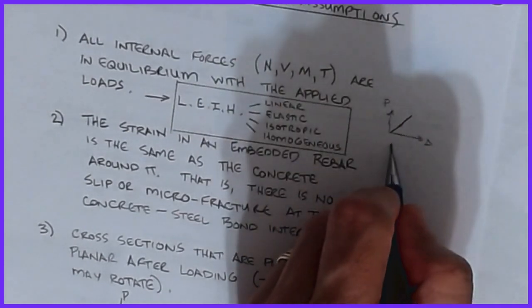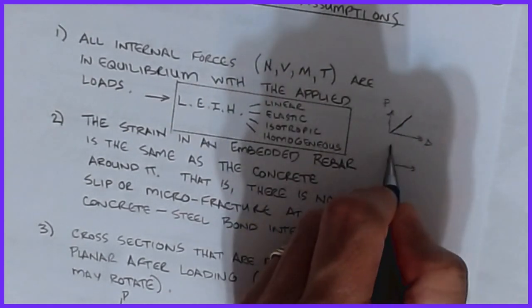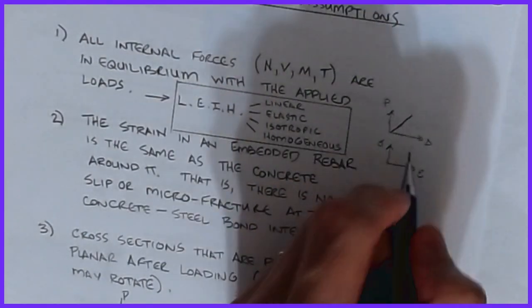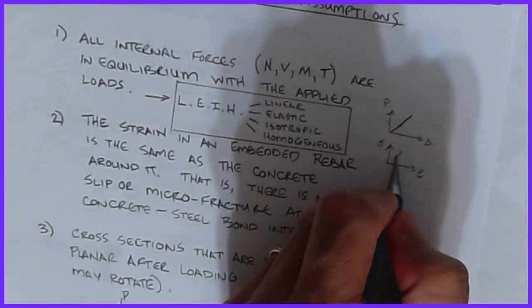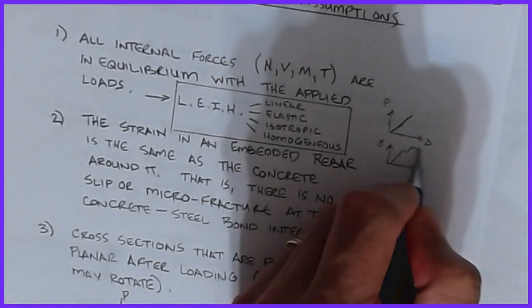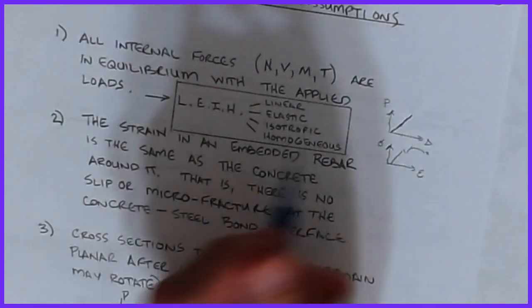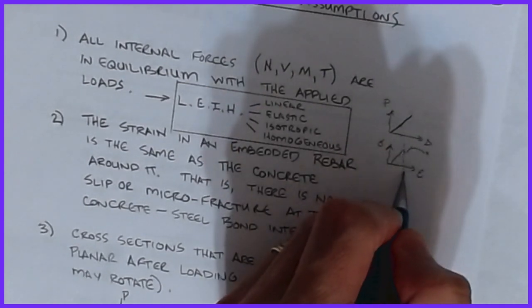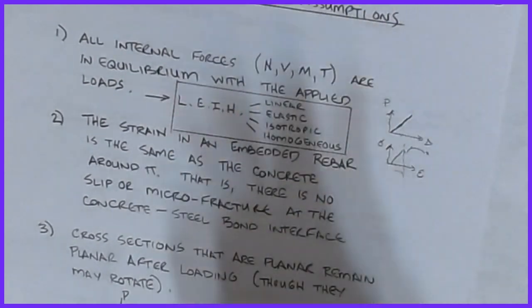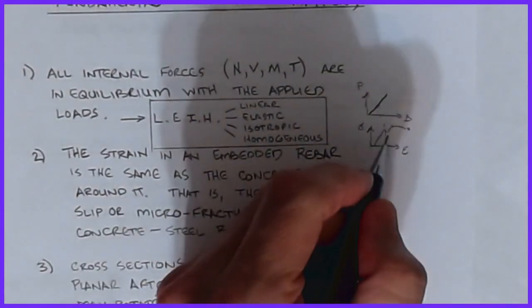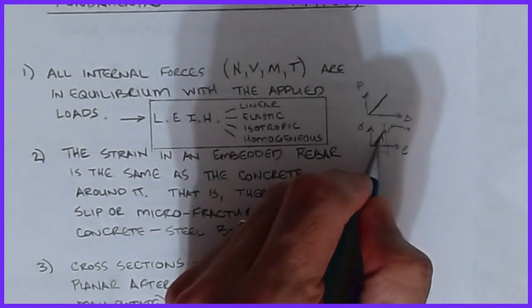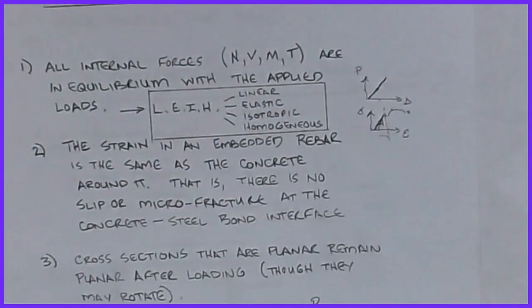The elastic portion is basically the relationship that exists between stress and strain. Remember, we said that for mild steel, the stress-strain curve looked something like this: you hit a peak point, and then it started to do something a little bit different. Elastic was everything up to that proportional limit and less. It's the region that is basically a linear function of stress and strain, because remember that the slope of that line was E, or Young's modulus.